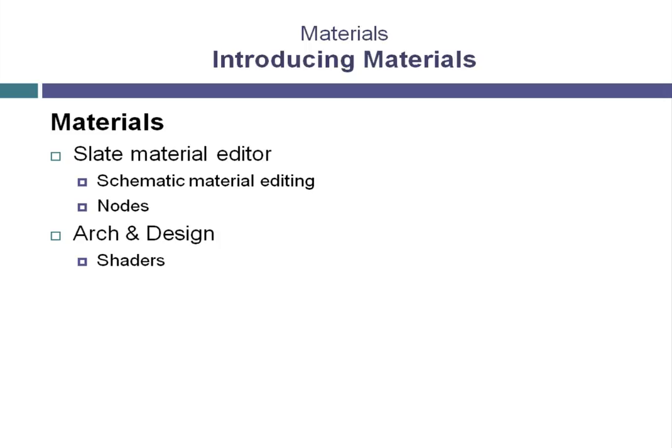We'll look at the process of mapping. We've just learned about using the map scalar modifier to map a pattern of roof shingles onto some geometry. Here we're going to look a little more in depth and learn how to get some more control over our mapping. We'll then look at the important process of applying multiple materials to single objects.